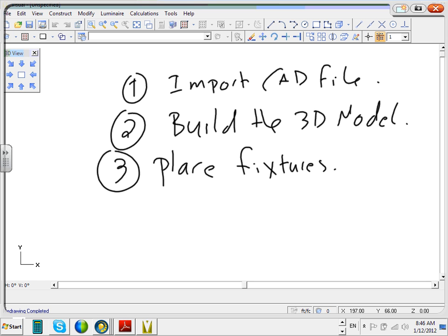This is when you use something called an IES file. We drop the luminaires by picking the IES file. You're going to see the IES file that we did. When we drop the luminaires, this one is going to come very handy to you. When we drop them, the Lithonia book and the sheet that I gave you yesterday must be right next to you, because based on these are the luminaires I'm going to be picking for every place. Otherwise, you're lost. Cool. So make sure you keep them handy.